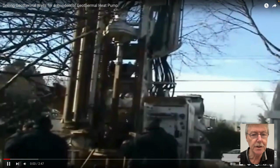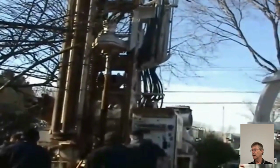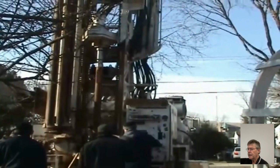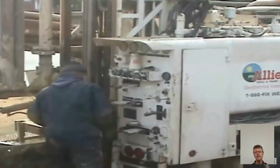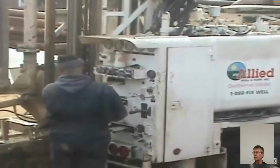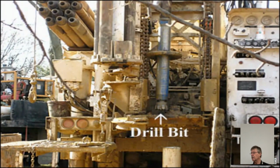If you're an energy engineer and you want to drill holes for different reasons, ground sourced heat pumps are a big thing these days. You drill a hole, not so deep perhaps, just to get below the frost line, maybe 2 meters, 6 feet down, where the temperature doesn't change very much. If you go into the ground here, anything below 6 feet to 1,000 feet, the temperature is something like 55 Fahrenheit, 10 degrees centigrade. And so you can use that low quality heat source, 10 degrees centigrade, to circulate water to pull that temperature up to a ground sourced heat pump, use it to provide the low quality heat in the heat exchanger, and take the cool out of that when it's 30 degrees outside.